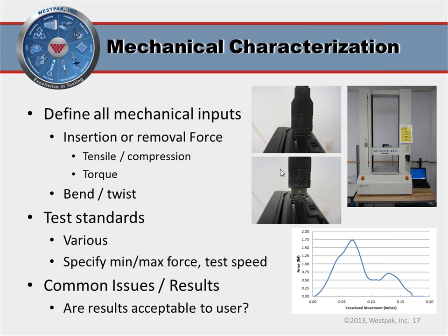One other thing with mechanical characterization is testing things to failure. So an example, the laptop has a little security lock. Put a security cord in there and pull it out. Is it actually secure? What force does that cord pull out? Things like failure on a power cord. So let's say I pulled a power cord apart somehow. Is there a shock hazard? So thinking about testing the level, characterizing what the typical user will see, and then also testing the severe, seeing how things break.